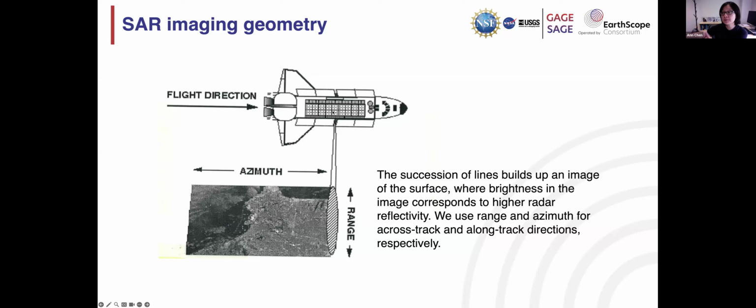In the Stripmap mode, the radar antenna points in a fixed direction, and then the next time it moves a little bit forward and makes another acquisition that illuminates a slightly different patch of the ground forward. As we keep sending additional pulses, you start to have a scan of the ground image.